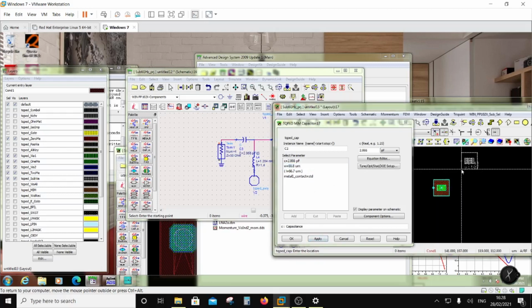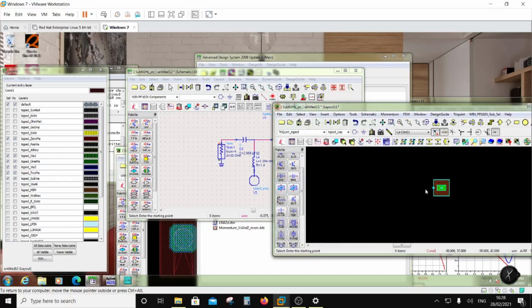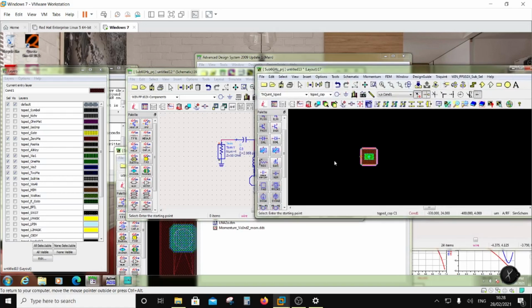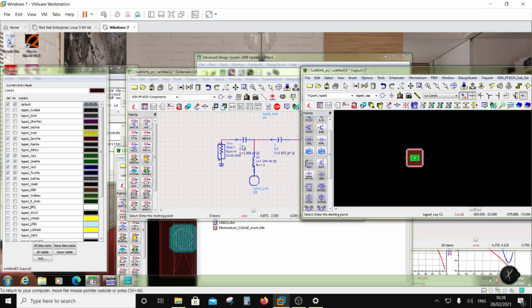So I'm going to use this capacitor as a series capacitor, and I want to make sure that the EM simulation of this series capacitor at my desired frequency of interest gives me 2.866, right? So then after that I'm going to create a shunt inductor and then put them together, right? So I'm going to break this part again and EM simulate this part. Okay, great, thanks.